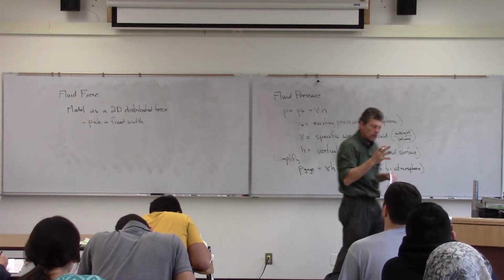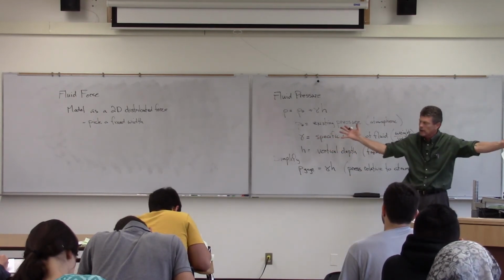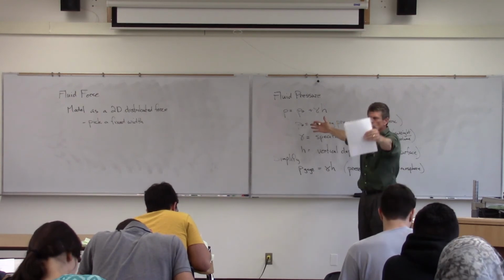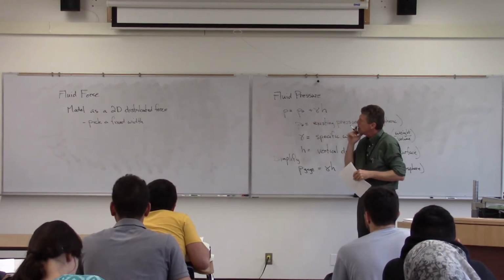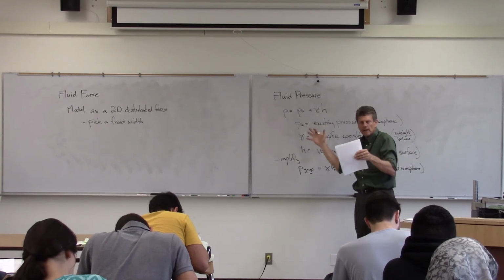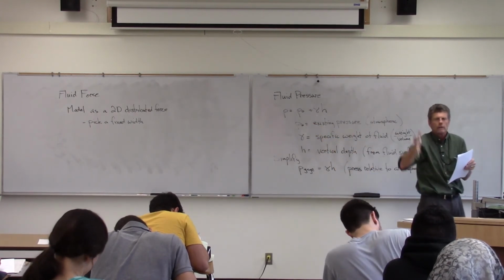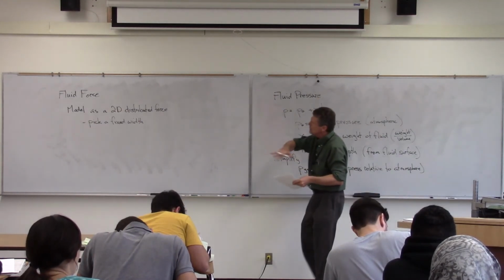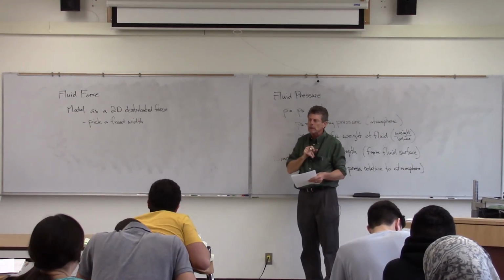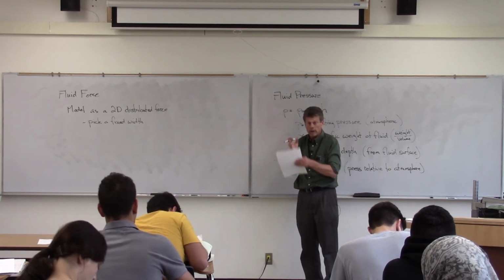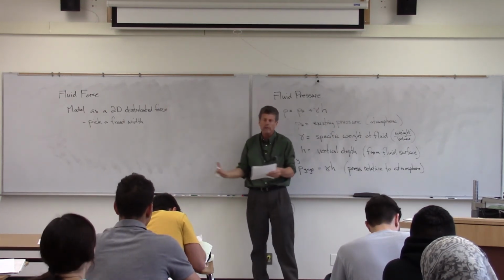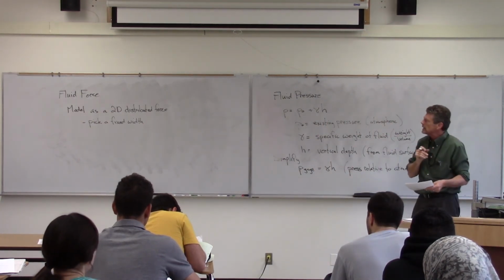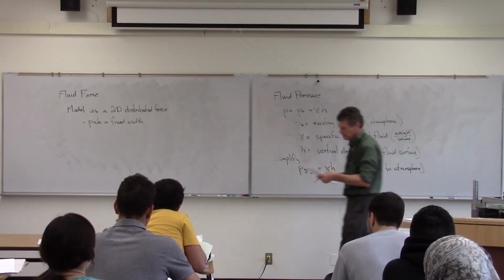What we're going to do with the fluid force, since it's acting on an area, is pick a fixed width. So I'm going to say 2 feet, 1 foot. And when I take that out of the equation, I take area out of it. Now all of a sudden I've got that beam equation that we just did. We've got a beam distributed load acting on that particular beam there. I have it in terms of force per length now. If I pick a fixed width, I multiply by whatever my fixed width is, I can convert it down to that level and then just simply solve it like I did with the beam load on beams.